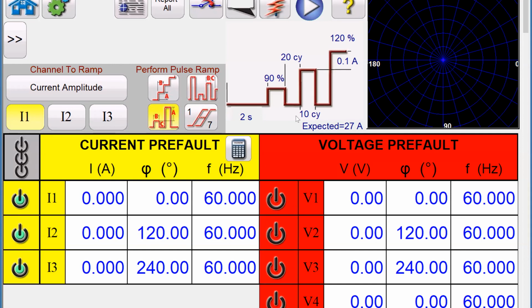So a 50 element is instantaneous, right? So what we want to do is pulse the current for just a small duration of time. We want to turn it off, or not really turn the test off, but not pulse anything, increment that value and pulse it again for another value. So we're going to increment at 0.1 every time the test set comes on and goes off. We're going to increment up 0.1. Then we're going to go again 0.1. And you'll see that here in a minute.